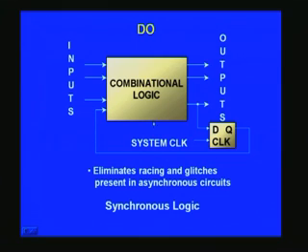And here you see that whatever is the combinational logic that you have inside, which will produce this output, will be processed only when the system clock arrives, that is at the rising edge if it is programmed for rising edge direction as such, and Q output is naturally delayed by 1 clock pulse, because this will take effect for the next iteration, or whatever you call next processing, only at the next clock pulse.